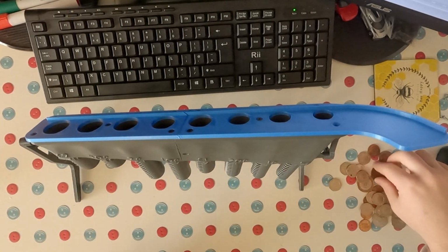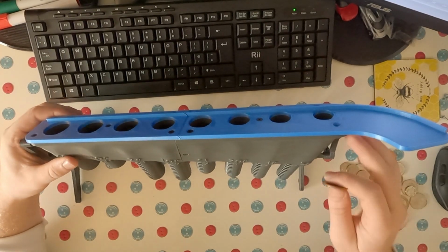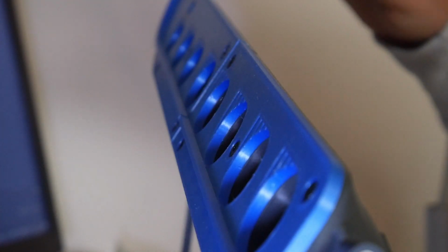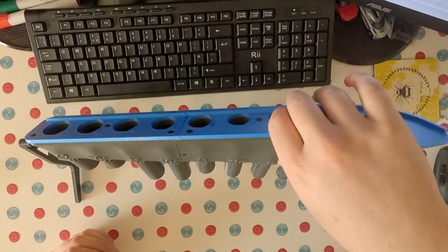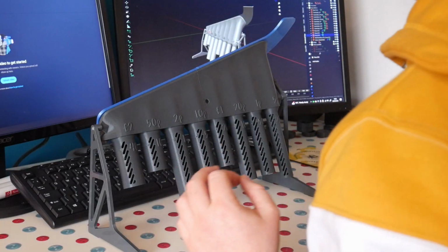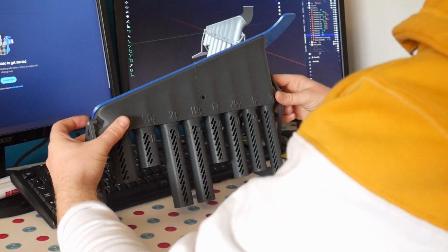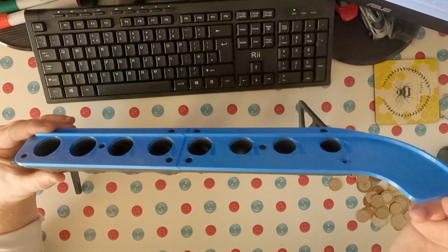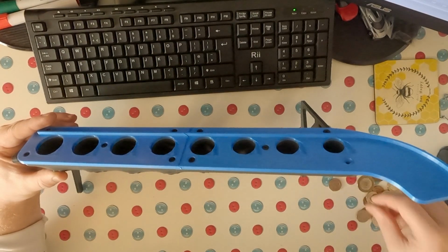See, there you go. This top slide plate just takes the coins down a bit fast, and it's at such an angle this way that the coins sometimes hop off rather than fall in. And there you can see that my tolerances are also just a little bit too tight on some of these. But if I bring this forward and then decrease the angle, this is an improvement I could make later just by changing the legs or the angle of this plate. It just makes it work so much better.